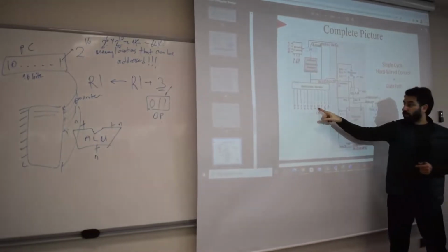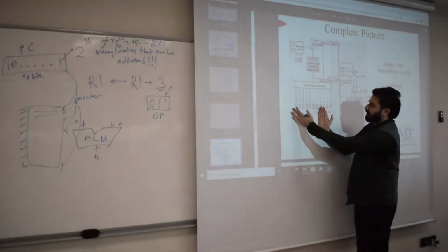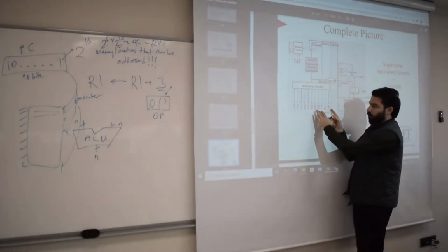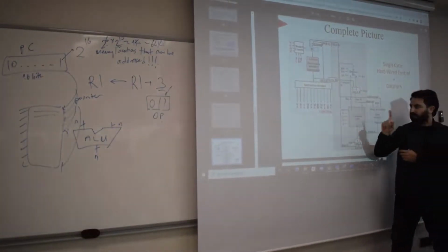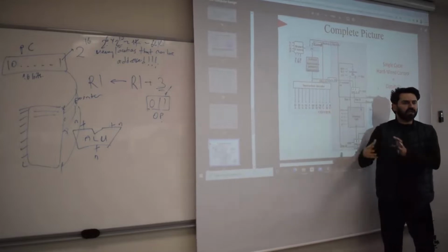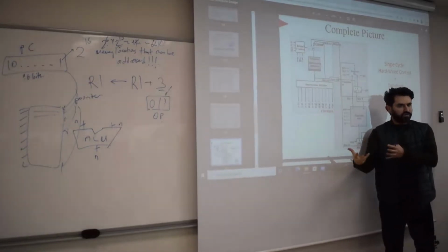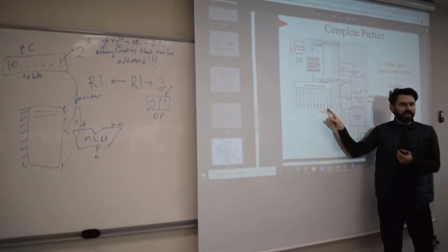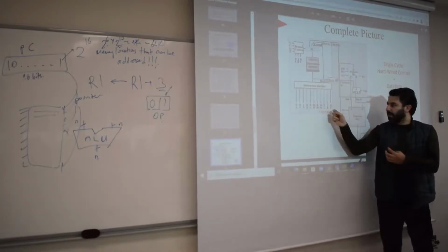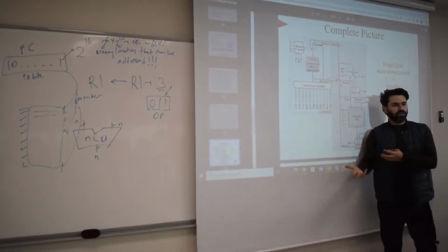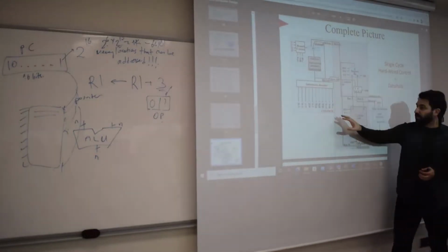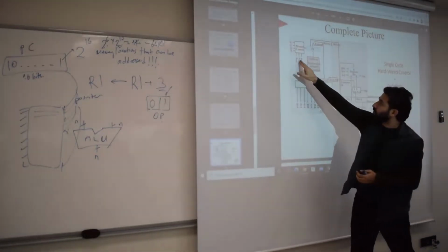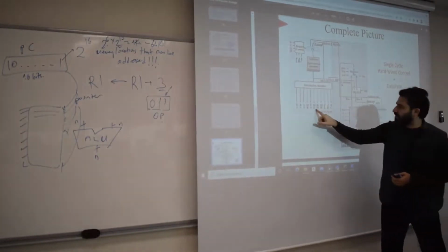MW is new now, right? Because up until here we have 16 bits already. Now these are new ones. MW is the memory write read, 1 bit. PL: is there any jump or branch or control instruction or not? JB: is it a jump or branch? And BC: which branch? Branch on 0 or branch on negative, okay? So we got everything now set out, because you see BC, JB, PL are connected to here, MW here, and the rest of them you already know.